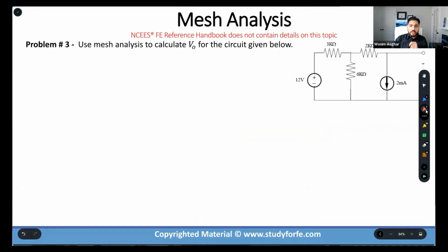Okay, so let's do one quick one, guys, and then we will get into our Q&A. So over here, when we are doing mesh analysis, this actually is very easy, right? The issue is that I'm asking you to calculate voltage across the current source. What did I tell you just recently? We cannot directly calculate a voltage across a current source, and we cannot calculate a current passing through a voltage source directly. Okay, so when I write my loops, first of all, both of these have to be equal. I mean, the same direction, correct?